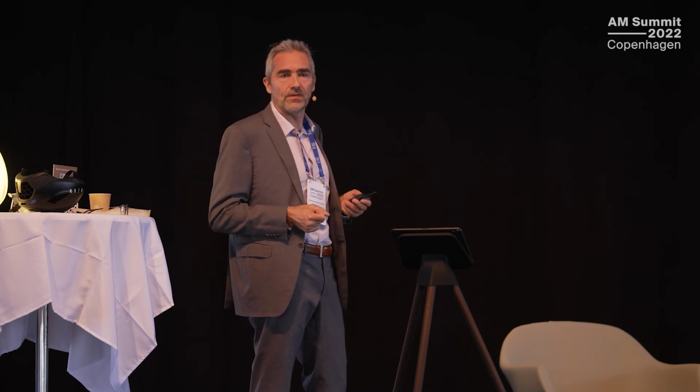Yes, maybe my part is more expensive to make, so from a manufacturing standpoint, this is not viable, but I save weight, meaning for an airplane, we had a case of brackets. Replacing all the brackets with an additive manufacturing process was more expensive, but we could save 200 kilos on an airplane. Meaning what? Less fuel consumption, or maybe flying an additional passenger. So the equation for the economy of the whole thing is not just about the process, but really look at it from a holistic standpoint to integrate everything to calculate the value of additive manufacturing.